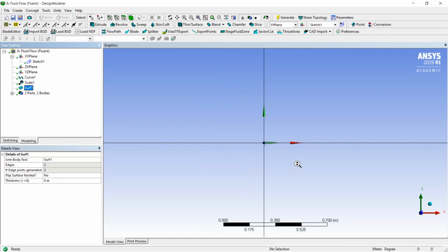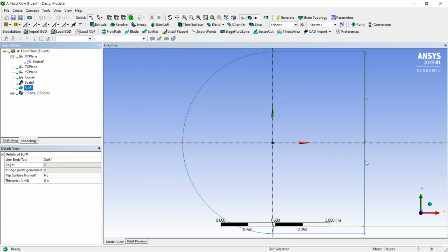First of all, to do that, I will have to create external volume of the simulation and then split this volume into more simpler volumes. The idea is that we must obtain quite simple and small volumes, then we will be able to control the quality of the mesh in every zone, especially near the airfoil, with a good precision. So I will start from generation of the volume of the flow around my airfoil.